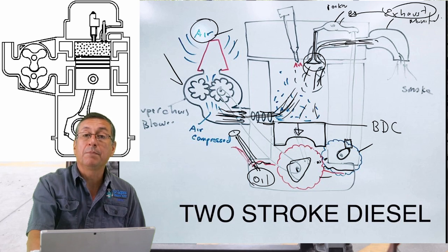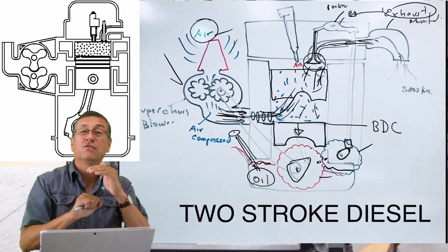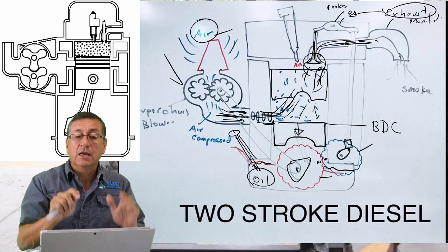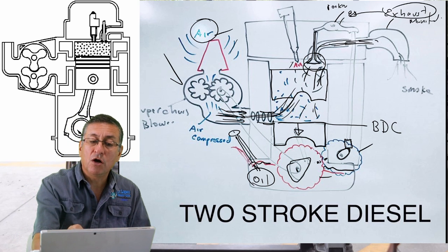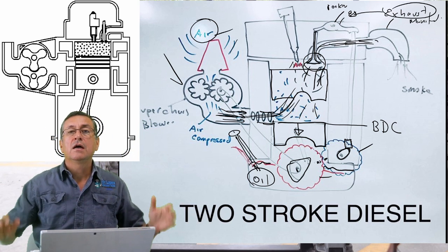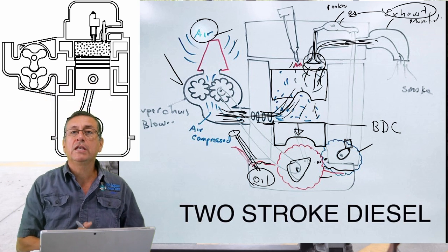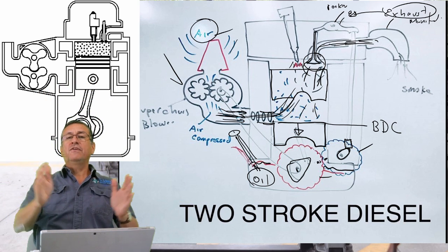And after that, the piston starts to go up. When the piston is pretty close to the top dead center, the air is fully compressed, only air, and immediately the injector opens and sprays the fuel, and the fuel ignites with the air, and the explosion is produced, and once again the piston is going down. All right, it's very simple.